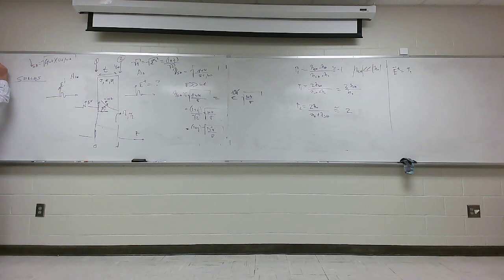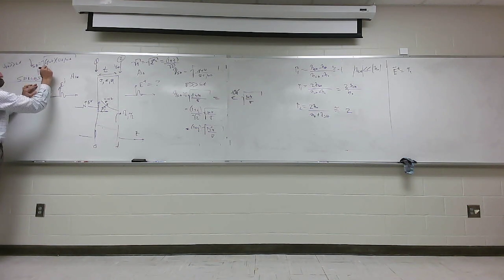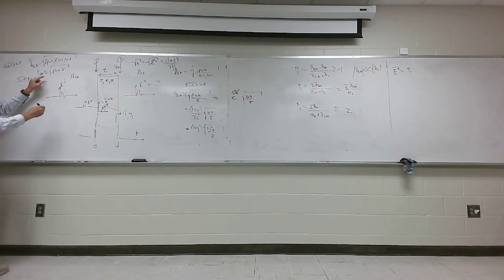If you assume that sigma of the shield is much greater than omega epsilon, which it is, gamma of the shield will be approximately equal to the square root of j omega mu times sigma. Y'all see how I ignored the omega epsilon? With me? Now, what happens then?